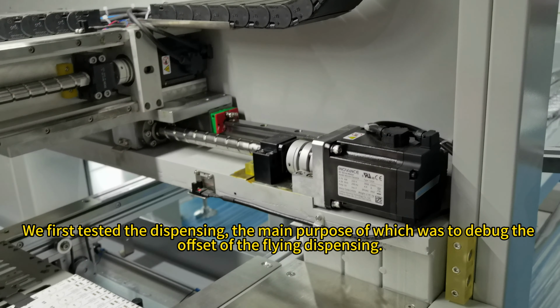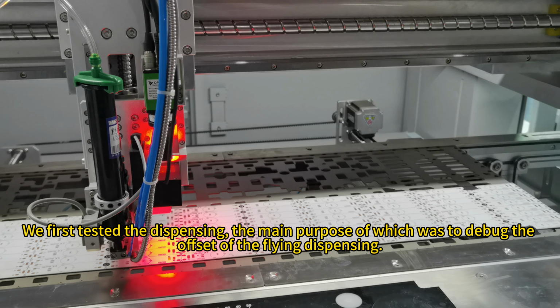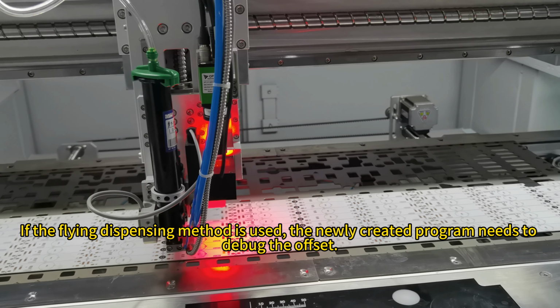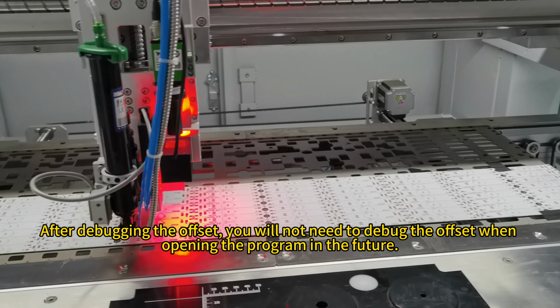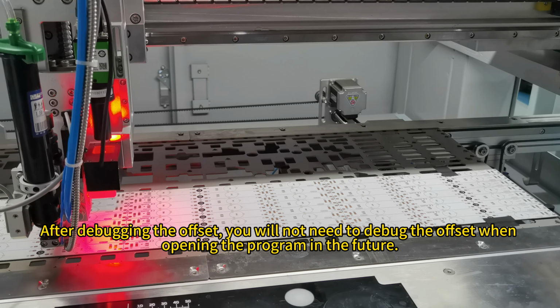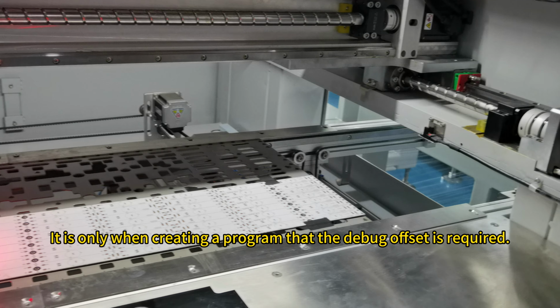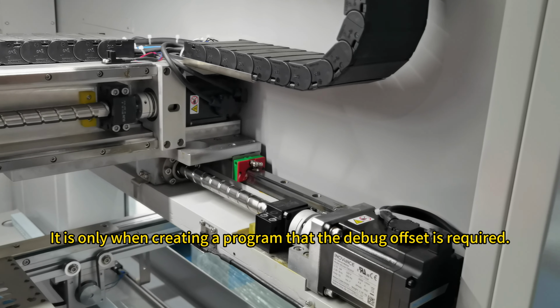We first tested the dispensing, the main purpose of which was to debug the offset of the flying dispensing. If the flying dispensing method is used, the newly created program needs to debug the offset. After debugging the offset, you will not need to debug the offset when opening the program in the future. It is only when creating a program that the debug offset is required.